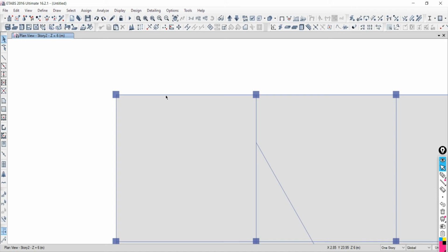If we want to check just dimensions and don't want to draw dimensions permanently, we can use the draw dimension lines option, or we can even use this pick 2 points option in the move command. The replicate command is not needed at all. Move command and replicate command are totally different things. That's another concept, and there is no role for it in this requirement.